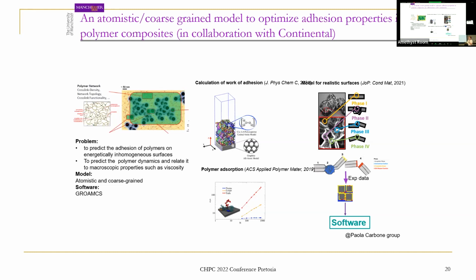But one thing they have to add are solid fillers. For the cheap tires for trucks, these solid fillers are carbon black, for example. This addition of fillers is to make processability easier, so they reduce the glass transition, but also to improve the mechanical properties of the tire itself. The problem is that when you add this carbon black into the polymer matrix,